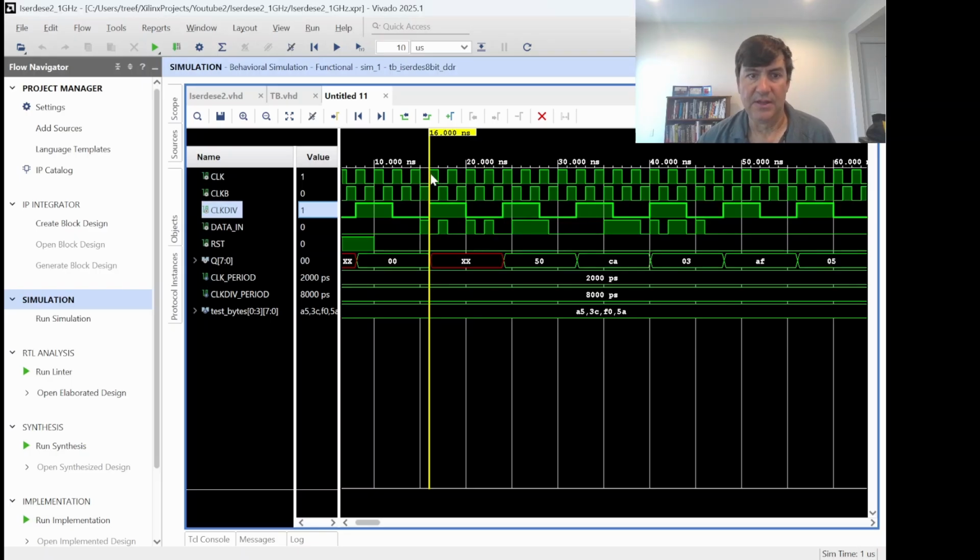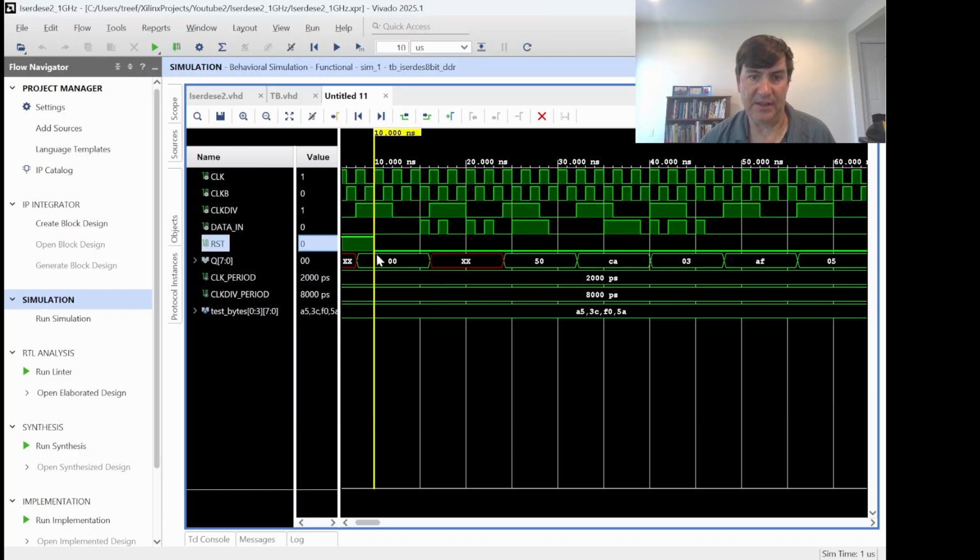We have the rising edge of the streaming clock in line with the divided by clock and in line with an edge of the data, but here we are getting collisions, and so that's really deceptive. How do you know if it's right? It must have to do with the relationship when coming out of reset.